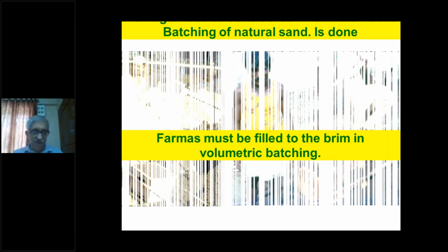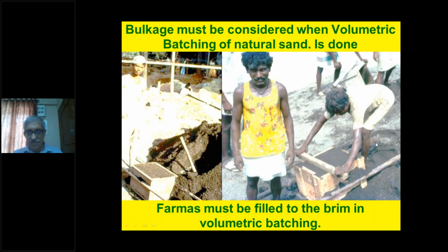One has to level the box properly. After taking the bulkage, you work out the requirement of the natural sand, and the measure must be filled completely and properly. This is extremely important. You cannot heap the measure or put a little less quantity in it.